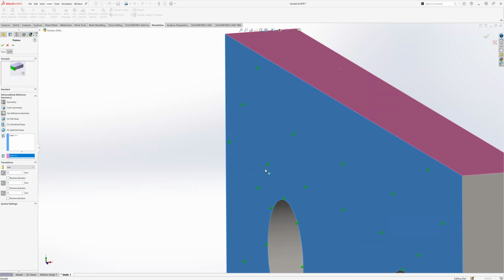So when you have that, this can be very useful, especially if you're just trying to constrain motion in one direction. Let's say I'm looking here, and if I turn this around, I only want it to move in the X direction. I could go to maybe this face and constrain those 2 directions. I can constrain Y and Z, and then leave X open. So now it'll be able to slide back and forth, maybe because I have a roller slider already put there or something. Again, there are different ways that you can assign these. Any questions on fixed or on use reference geometry?